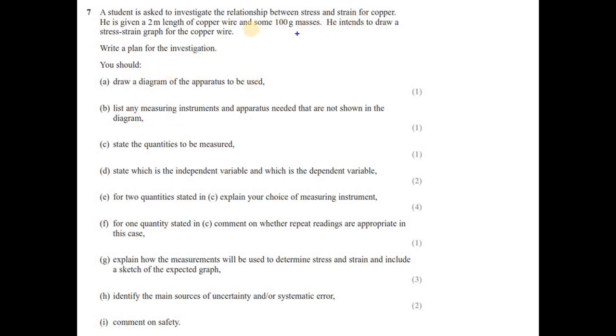Okay, this is all about finding the stress strain graph of a copper wire, and there is a typical diagram. You can use a horizontal plank in which you mention some U-shaped clip and a wire passing over a pulley.